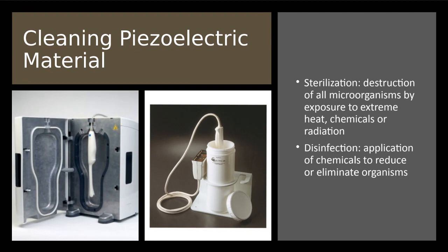Now, you may have seen in hospitals, or you may have worked in certain situations where surgical tools are put in an autoclave, that very high temperature sterilization process. Would we put a transducer in an autoclave? No, because that's going to go way beyond that Curie temperature, and it's actually going to damage the piezoelectric material in the transducer.